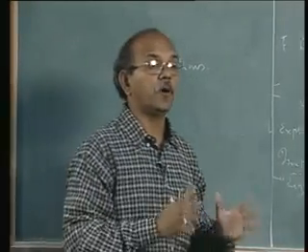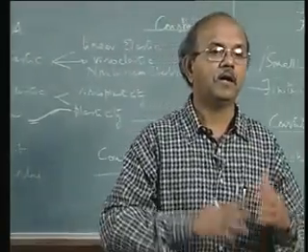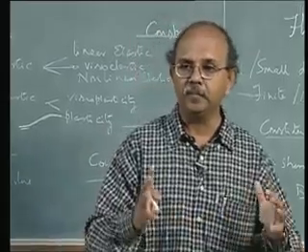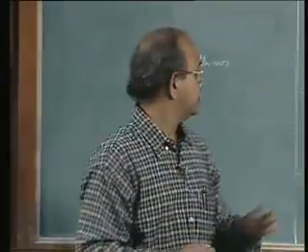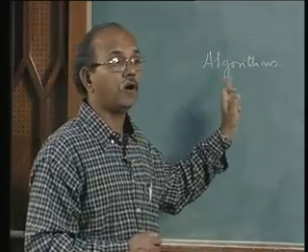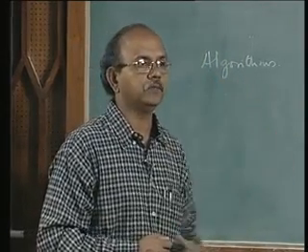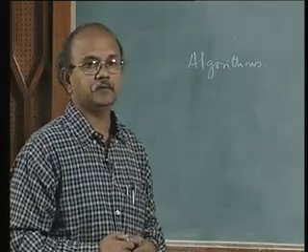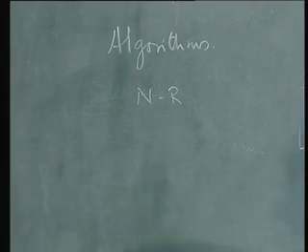The most popular among them is the Newton-Raphson scheme. You have other schemes as well, BFGS and so on, but 90% of the problems are solved using Newton-Raphson scheme. So this is an algorithm for solving the nonlinear equation. This can be employed whatever be the problem. So you have NR or Newton-Raphson scheme for solving the nonlinear equation.